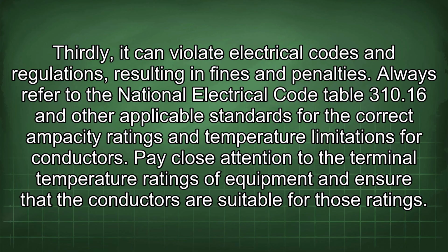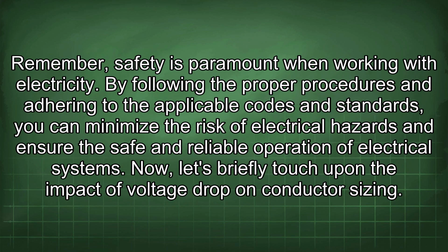Always refer to the National Electrical Code Table 310.16 and other applicable standards for the correct ampacity ratings and temperature limitations for conductors. Pay close attention to the terminal temperature ratings of equipment and ensure that the conductors are suitable for those ratings. Remember, safety is paramount when working with electricity. By following the proper procedures and adhering to the applicable codes and standards, you can minimize the risk of electrical hazards and ensure the safe and reliable operation of electrical systems.